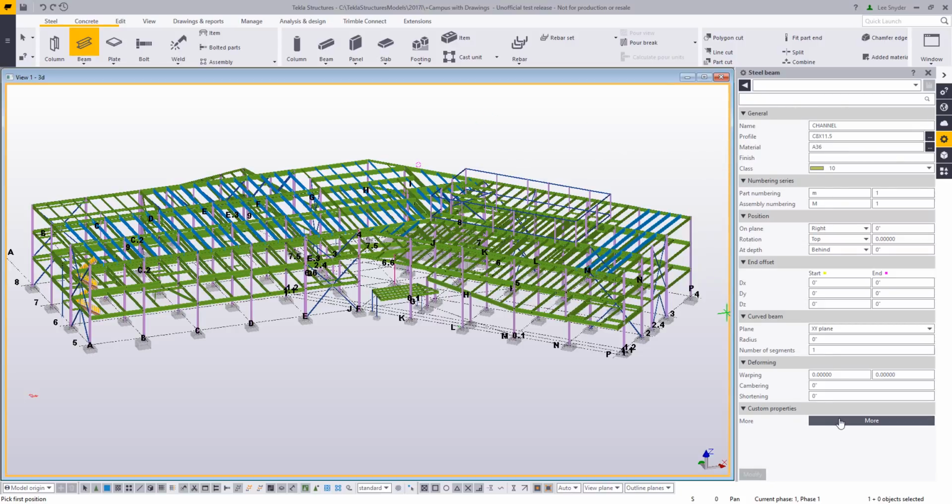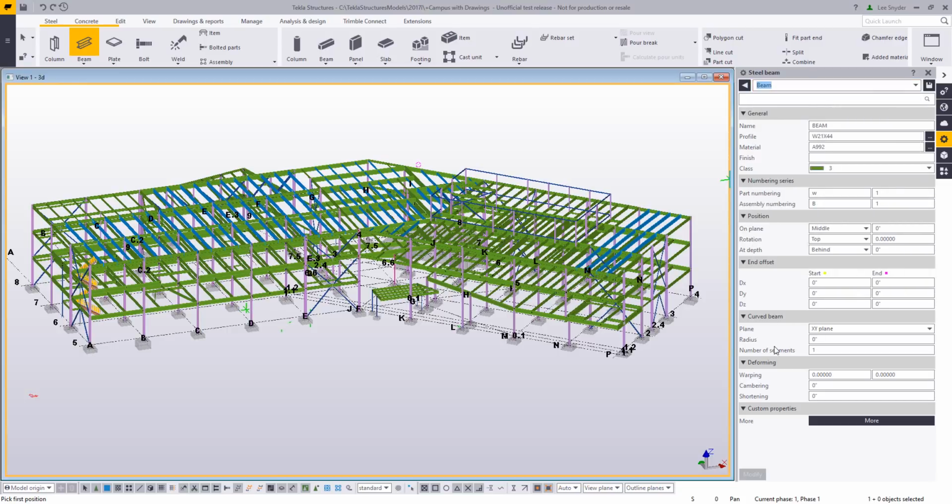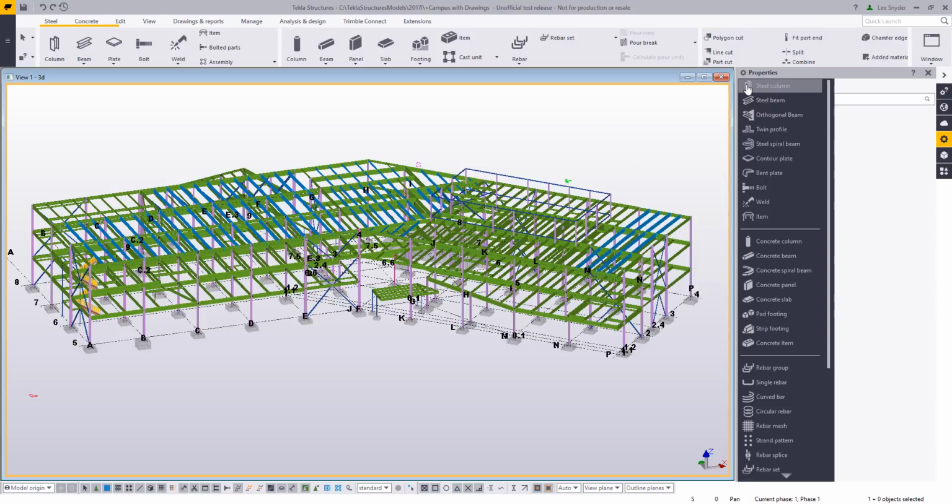So these settings here are automatically applied. My command is active here, and I can just pick a start point and an end point to model that piece in. I can also come in and load my attribute settings. Those are automatically applied, and now when I click my part or piece, that will be inserted there into the model.